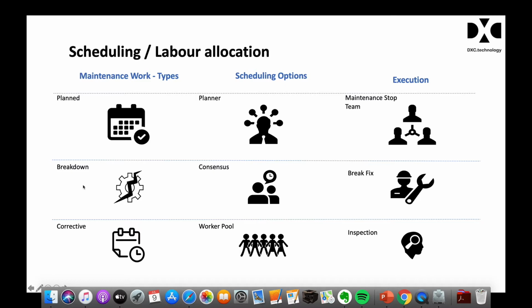The fourth type is really the process of a maintenance stop. If you do have situations where the plant is down for a particular period, either a planned downtime or something has happened to it that it's not working for a particular period because it's missing a part, you do have a maintenance intervention opportunity. That then allows you to look at the overall view of the plans that you've got and pull work forward to take advantage of the time when that machine is down.